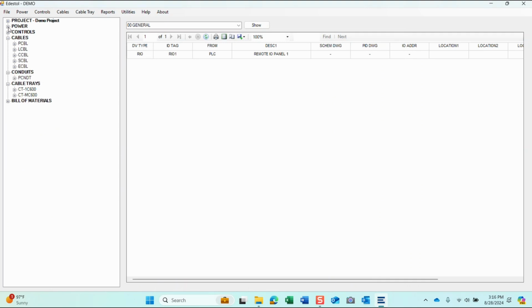The nice thing about the program is there are 2 data files that are necessary to run it. One we call user data, which has the manufacturer's information for, let's just say, adjustable speed drives, all your different cables. It gives you dimensional information, input ratings, things of that nature that you wouldn't normally have access to. It just makes it a lot simpler to pick out of a list. It also has ratings for bus sizes that are potential and stuff like that. And it also has your report specifications, so you can change the format of each one of these summary reports with what columns you want to show as well.